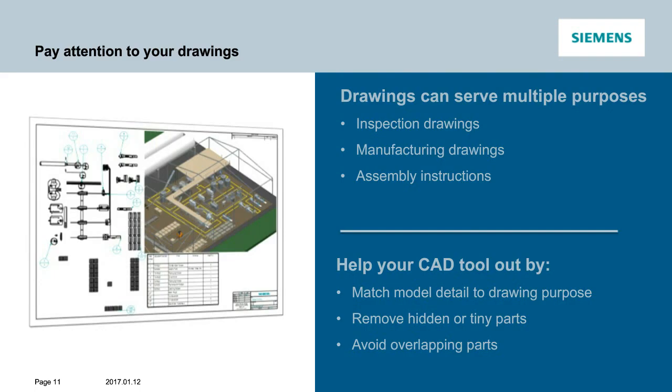Drawings have a big job when it comes to large assemblies. Multiple views of each assembly, including multiple parts, potentially cutaway and detailed or exploded views, mean that your CAD tool has to manage the display of a lot of different states of the model. From a performance point of view, it might make more sense to make multiple drawings rather than make a single drawing with multiple sheets. This can put a large memory load on your computer and may slow you down significantly. This, of course, depends on your particular models and the density of your drawing views on the sheet.